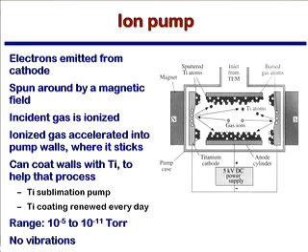So those are the four primary pumps that you'll see in the TEM. You'll see roughing pumps all the time. Increasingly, you will not see diffusion pumps, but instead see combinations of roughing and ion pumps. The advantage of the roughing and ion pump combination, again, is that it reduces the possibility of both vibration as well as having a vacuum problem associated with the oil going the wrong way.